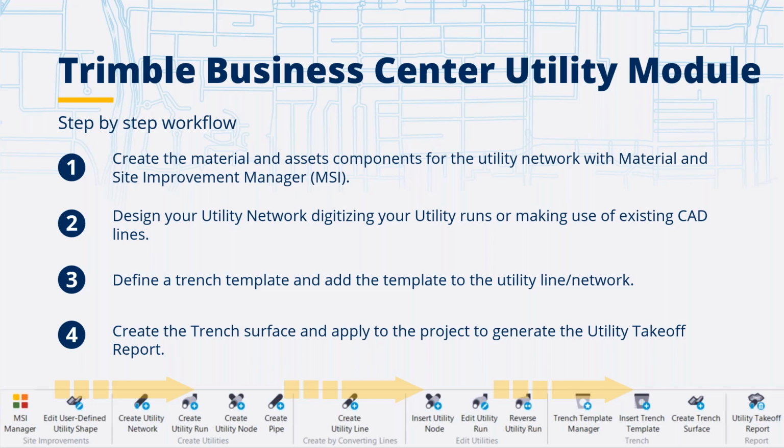And all of this basically can be finalized in the generation of a final report where the user at the end can see the extent of the trenches, the volumes of the materials which have to be removed or moved, the number of elements which are needed, for example, manholes, type of pipes, diameter per type of pipes.